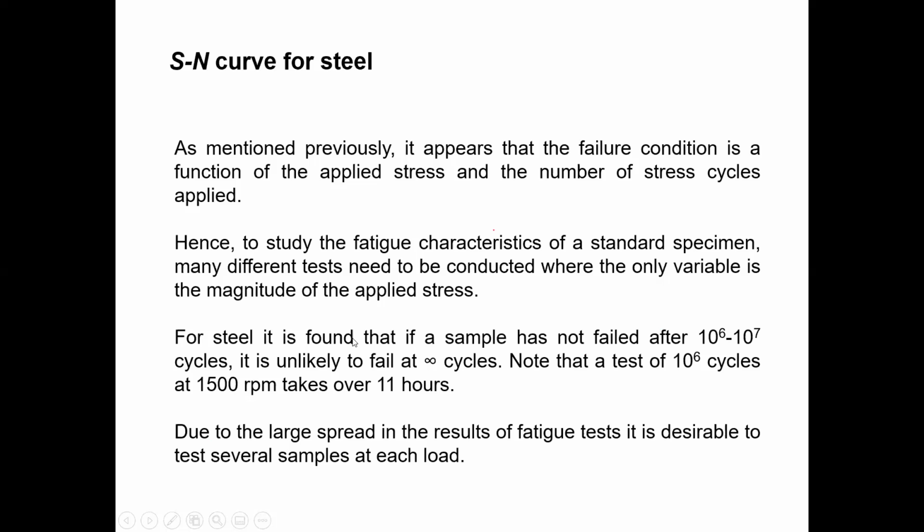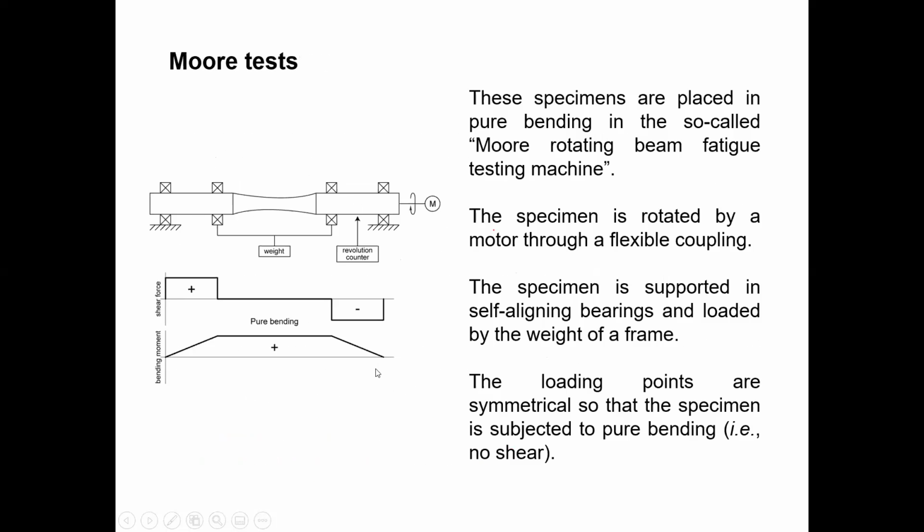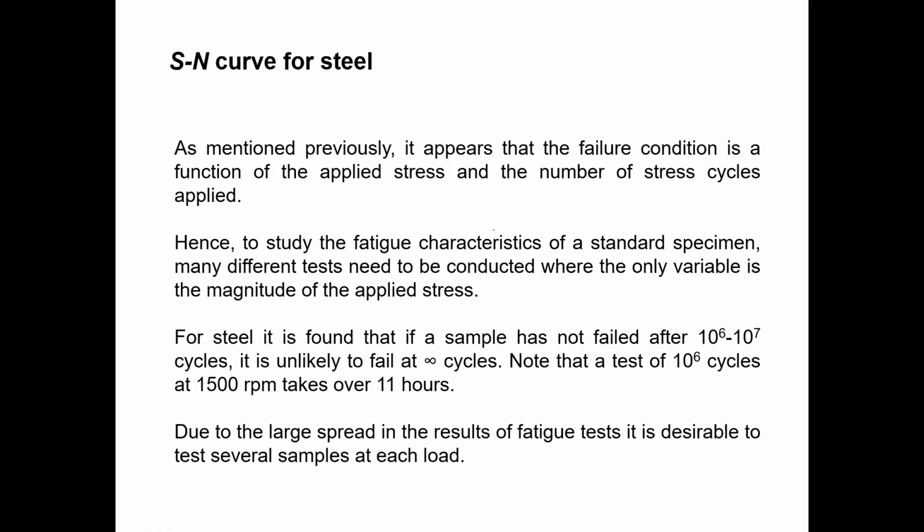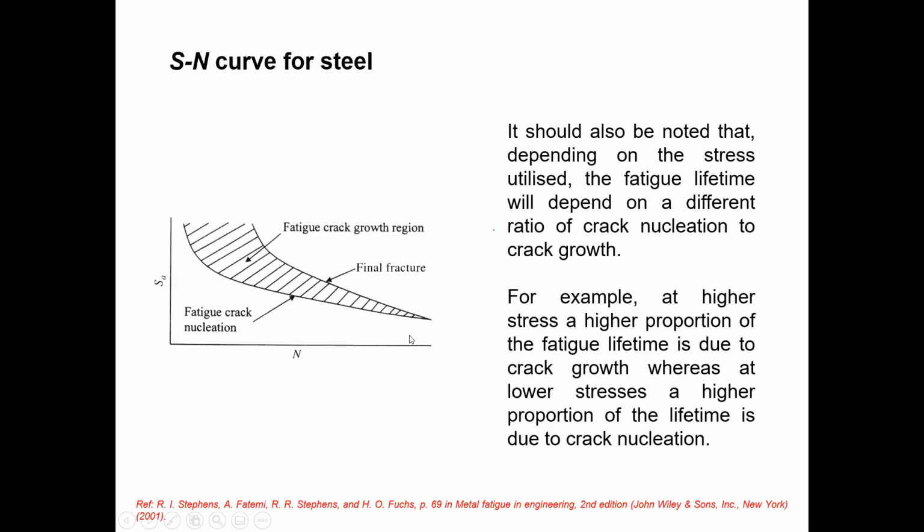Until the sample breaks, this specimen will be rotated and the load applied. That is the mechanism. Then they find out the number of days, or hours, and they also count the number of cycles with sensors. So we can plot the S-N curve there, because strength reduces with time. The S-N curve will be something like that.